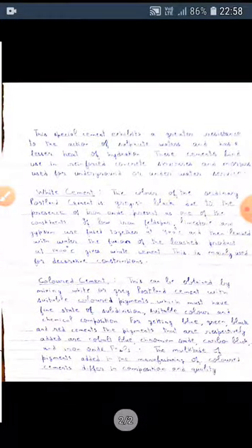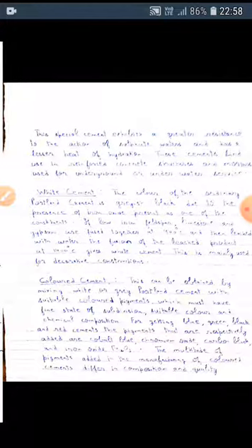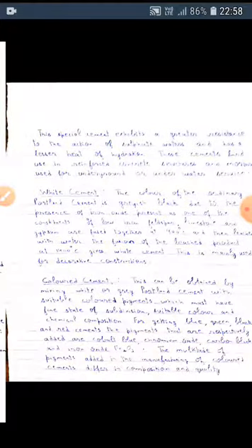This special type of cement exhibits greater resistance to the action of sulfate waters, and it is distinguished by a considerably lesser heat of hydration, that is heat generated by setting and hardening of cement, compared to Portland cement. Super sulfate cement is manufactured by grinding together the above constituent materials.